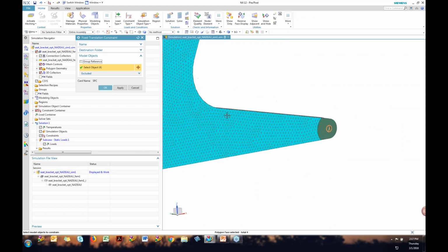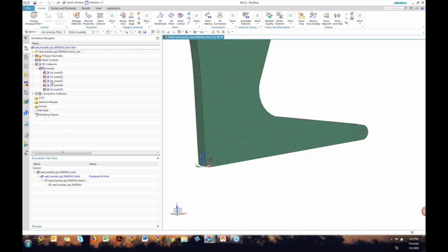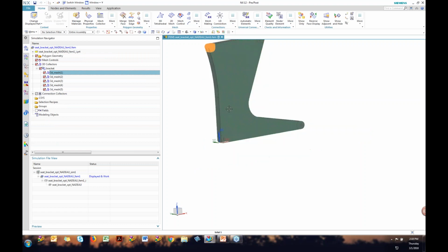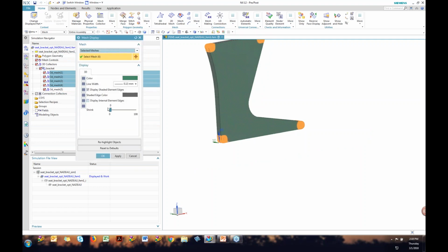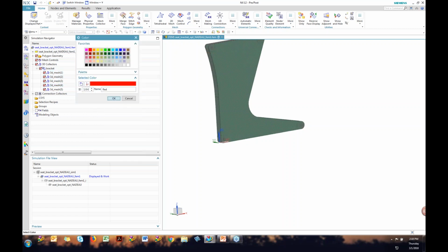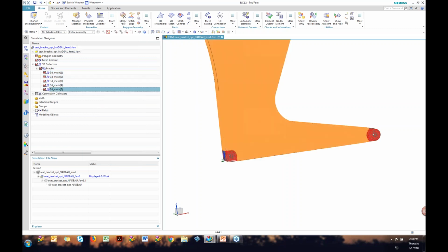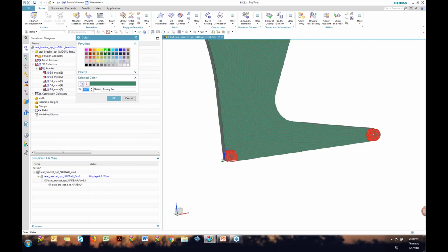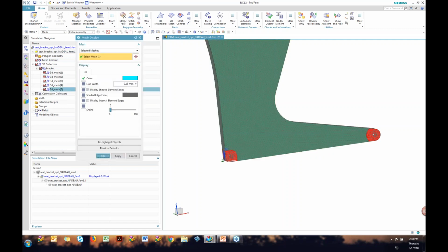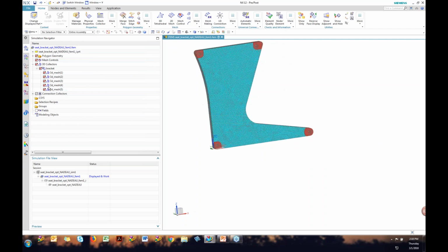So all you have to do is at the FEM level, if you go to the collector, you specify your mesh, and I'll just grab the other ones. And you just right click, and you can say edit display, and then right here is color. You can change the width as well, and you have some other options. So instead of green, give them red. And now if I hit OK, now those have become red. I apparently changed this one. Okay. Thanks. Yep. So it's just this display.